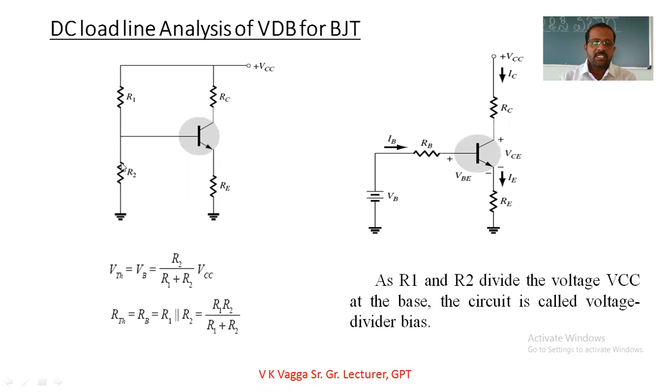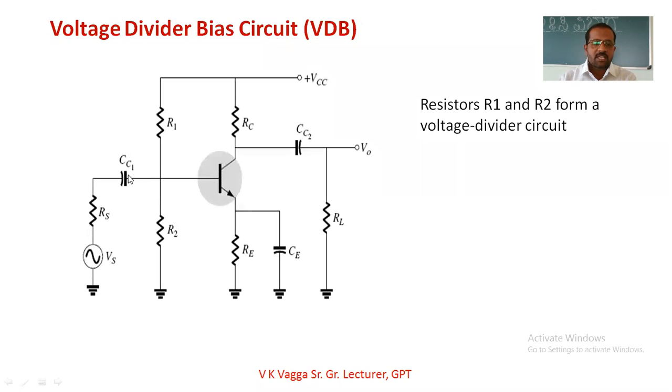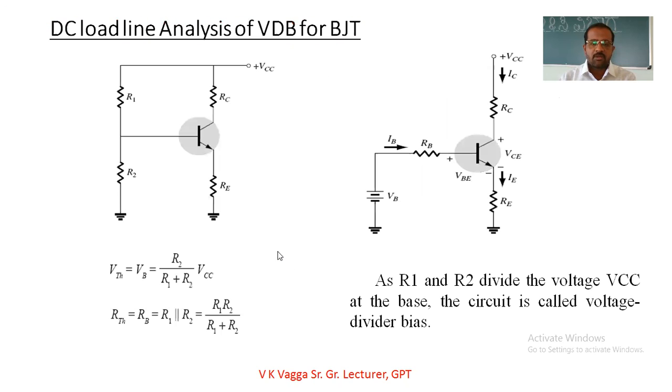For the DC analysis, all these capacitors act as open circuits. Open circuited means there is no connection with the input, no connection with the output, and no connection with the ground here, so that you can get the circuit in this way.